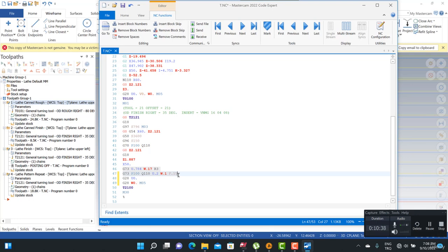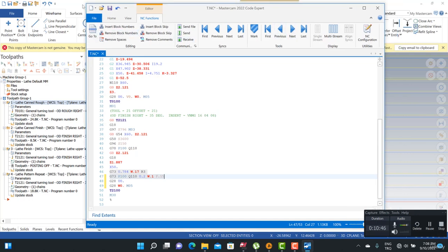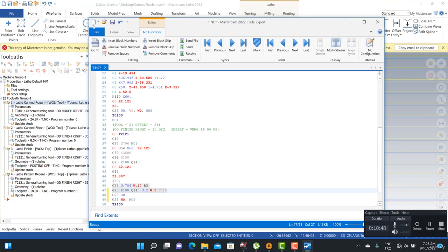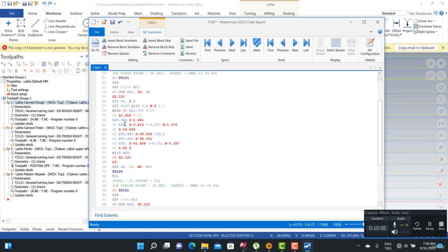Okay, if I am changing my radius, of course it's not possible to use that G code, because if I am changing my radius and compensation type, and the compensation type is calculated by the computer, it means that we cannot use that number anymore. We changed that because of using a different tool radius.